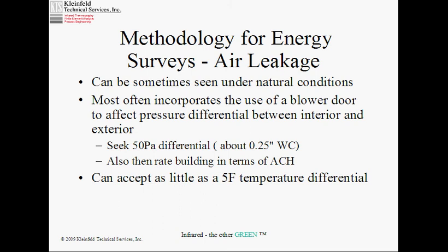Air leakage, which is equally important for both comfort and energy, can sometimes be seen under natural conditions. You will get some air leakage just as the building sits. And that sample I showed you of the ceiling was the building sitting, and whether because of wind or stack effect or the like, there was air leakage. I didn't do anything to generate it.